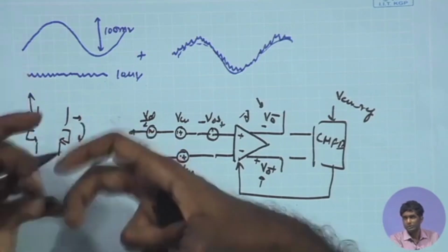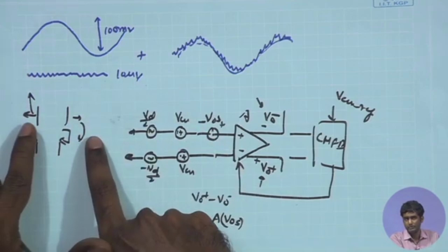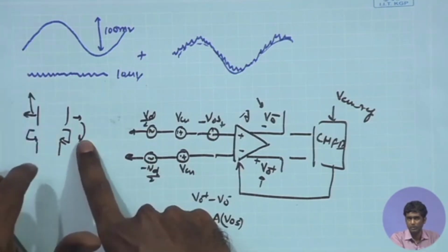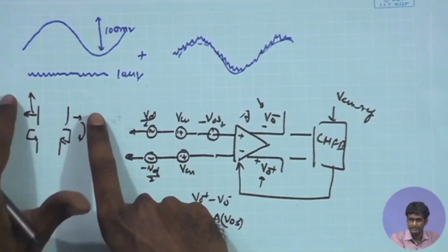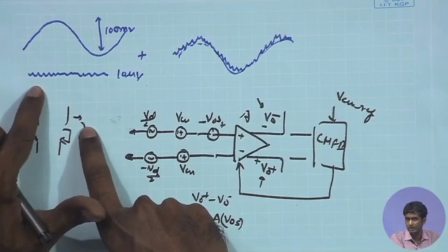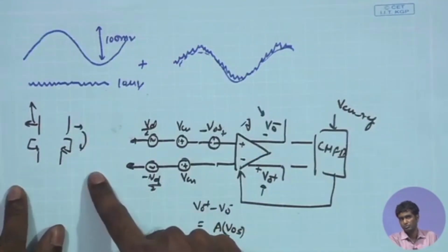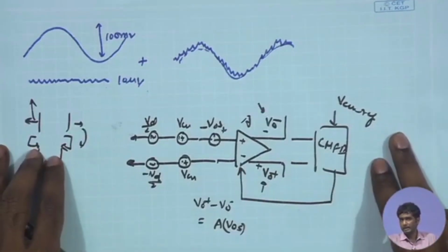And as a result, the signal swing that you can have is already very much minimized. You cannot go significantly higher or lower, because under DC condition, under 0 input, one side is approaching close to VDD, another side is approaching close to ground, which is not a very desirable characteristic.